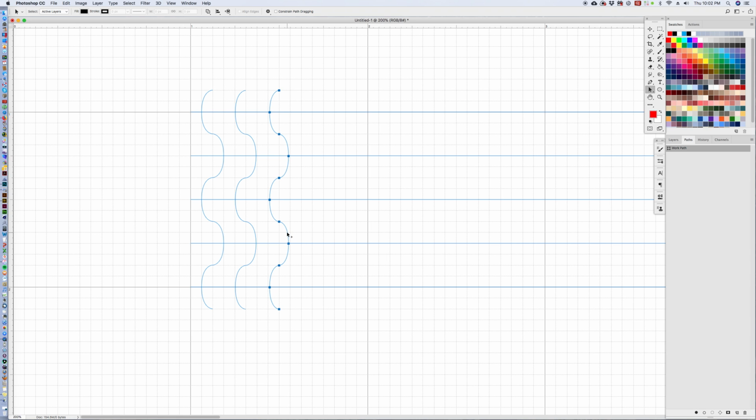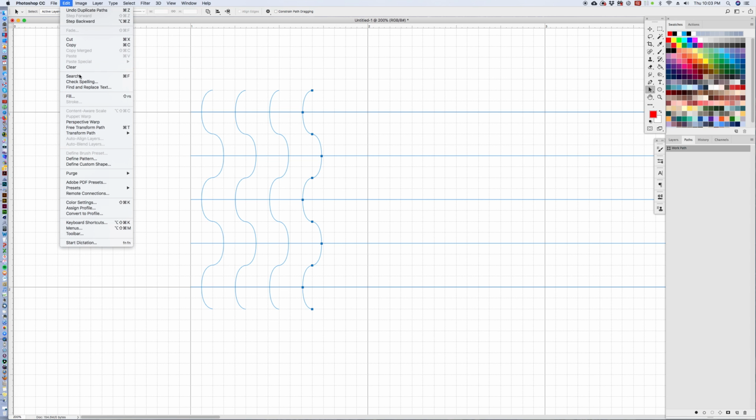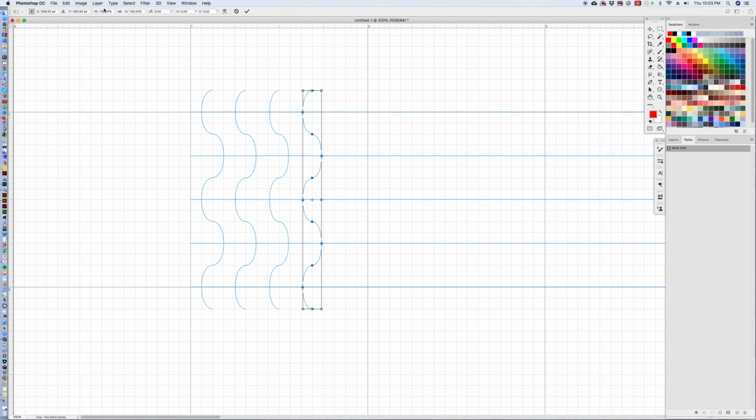Click and drag out using the option key, and you want to also hold down the shift key, which will lock it whichever way you're dragging it. And then after that, and you've made your duplicate, you go to Free Transform Path and reduce it again by 92%. And I want you to continue to do that until you've made 30 or 32 of them. I think that 30 will be enough. If you have to make a few more, then go right ahead.